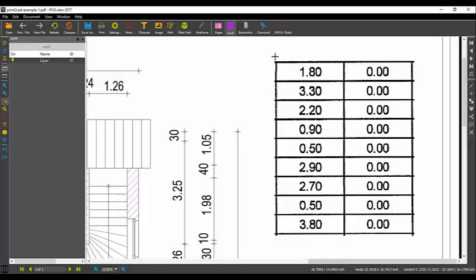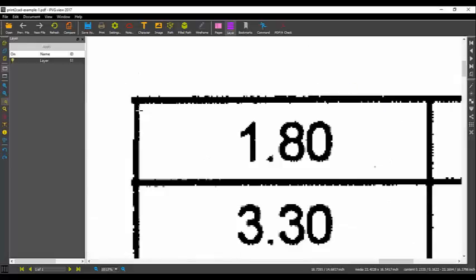And if you need this line as a real line, this is another thing. This is not a conversion. This will be a raster to vector method. And maybe you expect that it will be really a line here with a corner. Then you need a middle line tracing as a raster to vector method. There are a lot of different raster to vector methods.